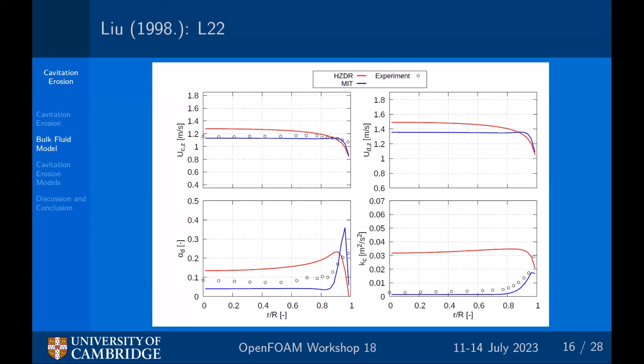So this brings me to a brief conclusion of momentum interchange terms, that there is no set guideline. It's very application based. It depends on your velocities, your phase fractions, and your application. So if you hoped that I would give you a best practice guideline, unfortunately, I don't know it myself.